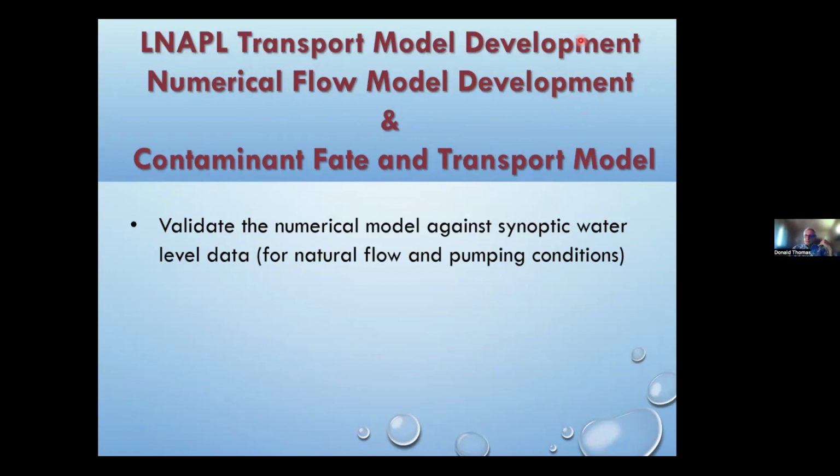The LNAPL transport model will be specific to the vadose zone, the unsaturated zone. Numerical flow model will apply to groundwater flow through this region. And ultimately then that will form the basis for a contaminant fate and transport model. As I mentioned earlier, we don't develop these models in a vacuum.